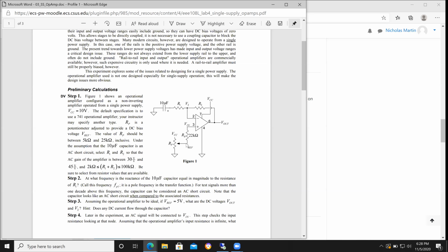Okay, then the last thing I'll comment on, maybe you've already figured this out, but once you go to build up your circuit, there are some potentiometers available for you in your kit. They're a 3-terminal device. I think they included even the little screwdriver too to adjust them. Here's what I recommend if you haven't done so already. The 2 outer terminals are your rail terminals, and they're interchangeable. It doesn't matter which one. You could hook one up to VCC and the other one up to ground, or vice versa, okay? The middle terminal is your tap point for your VREF.